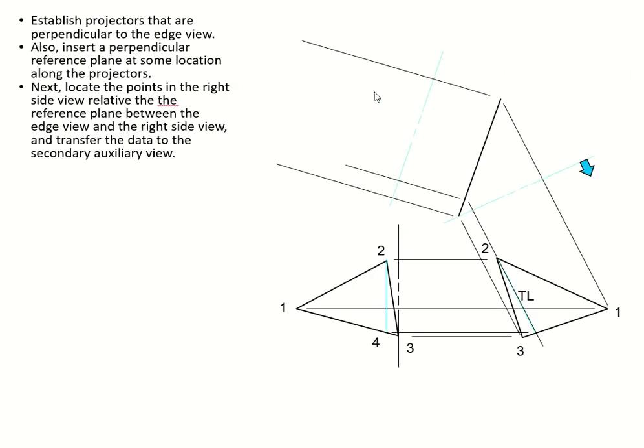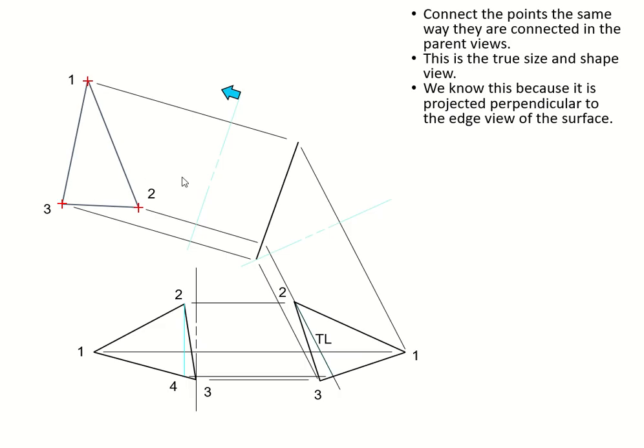We're gonna start our next projections. So extend all of your projector lines out through the third reference line, which is your fold line, in other words. And we're gonna draw our top view on this side. We start doing our dimension, drawing from the fold line to point 2, fold line to point 3, fold line to point 1, same as fold line to points 2, 3, and 1. Keep all the distances, then connect the points.